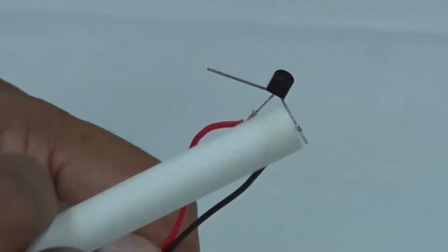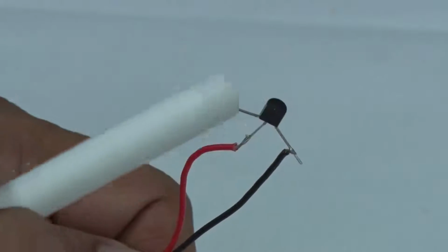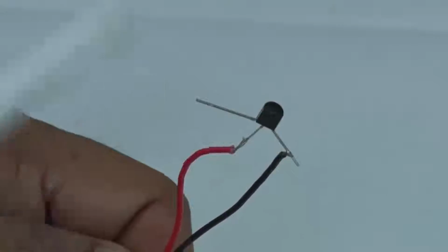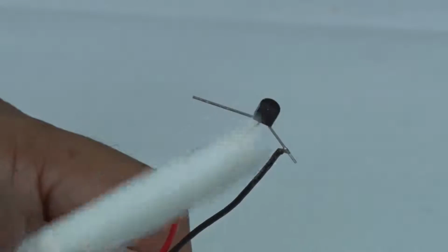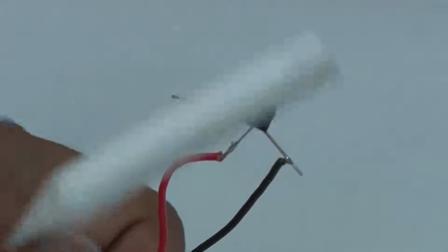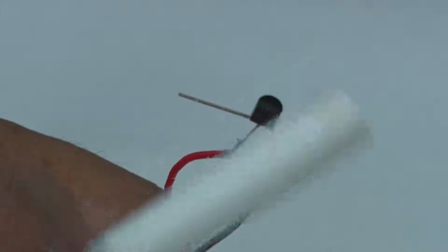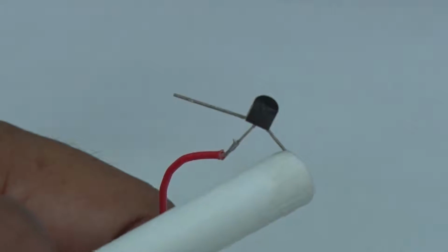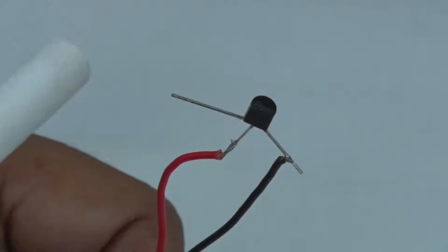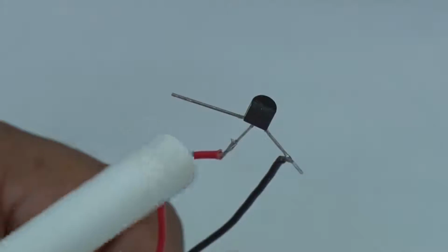Then you have other kinds of transistors where the casing is metallic and full cylindrical, and from the bottom 3 leads come out. In that circular cross section there is a notch from which people find the first lead, second lead, and third lead, and then the data sheet will say which is emitter, which is collector, and which is base.